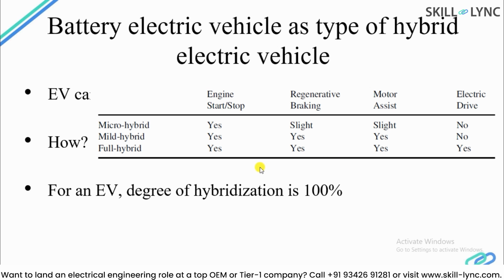Now, does that mean you have a CNG kit in your petrol vehicle? No, a full hybrid vehicle has a complex control strategy where the power sharing is determined. It is similar to a combination of IC engine along with electric, but the overall control is the master control, which decides which power is to be used from either electric or engine.